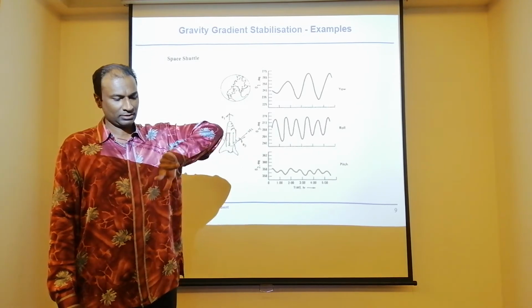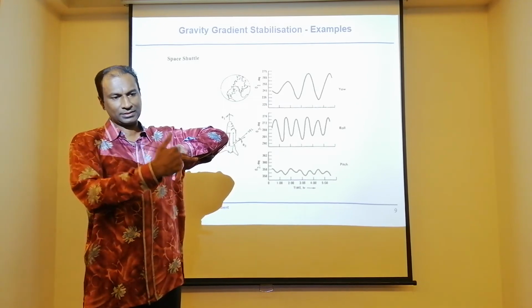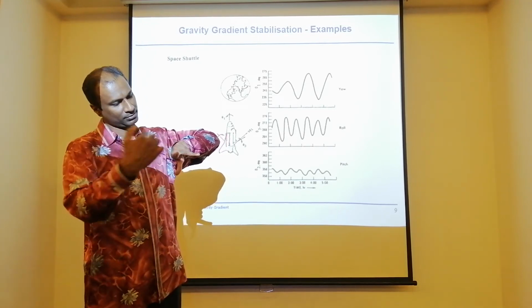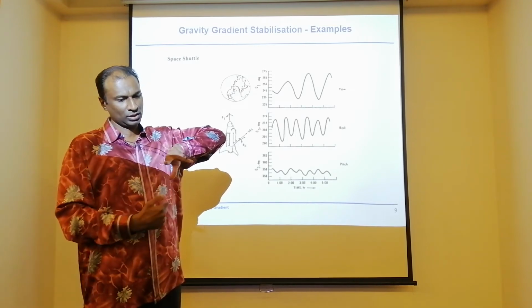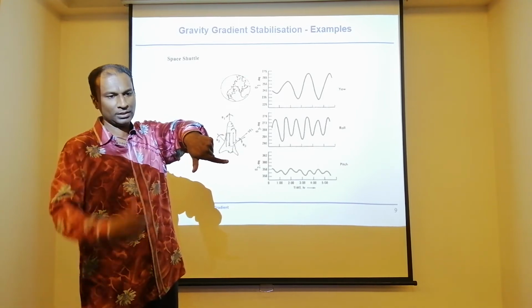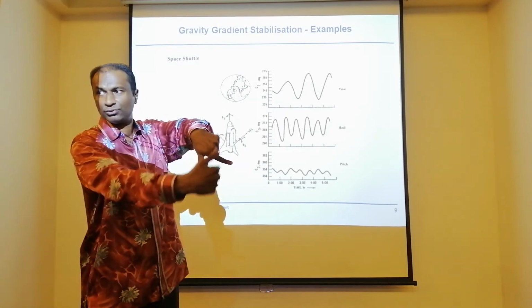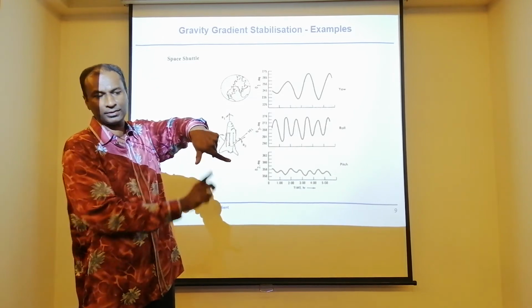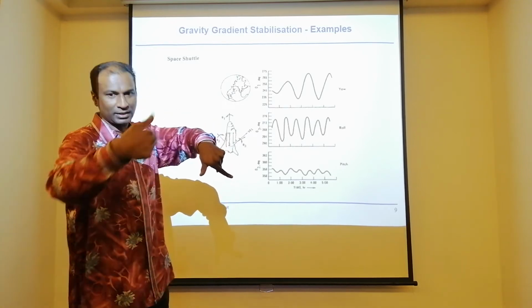Okay, flying. Now let's say there is a disturbance acting this way, let's say clockwise. When you see from there, it's clockwise. And this is roll. When I move here, my roll is here, and there is a disturbance here, and this disturbance no longer is going to affect the roll. It's going to affect the yaw now, because the nature of the disturbance is always, let's say, clockwise.